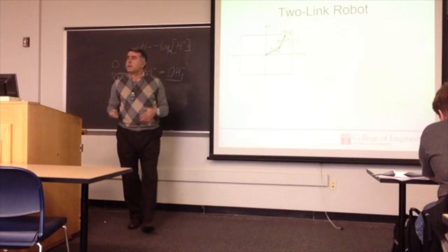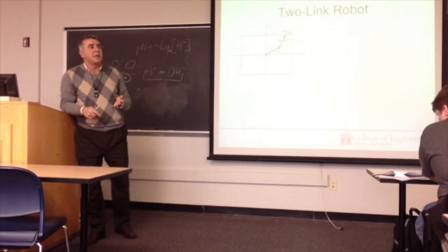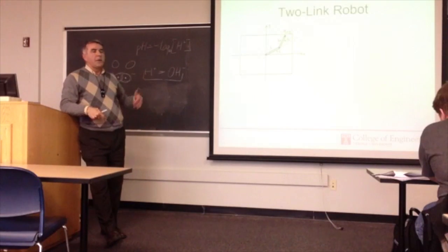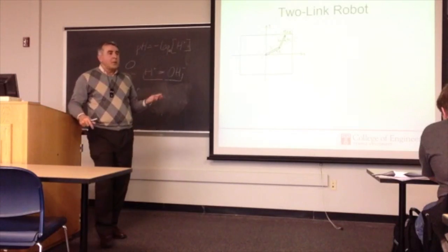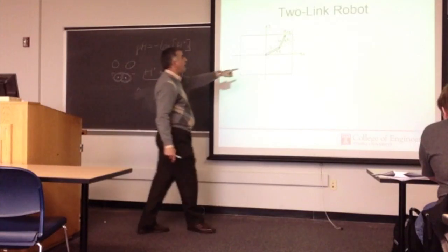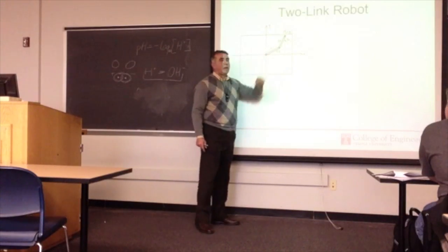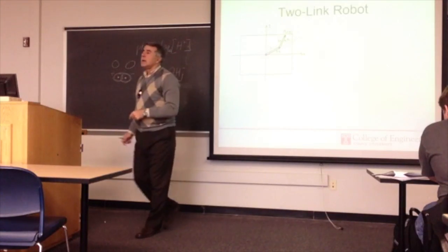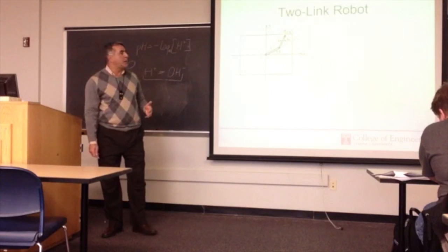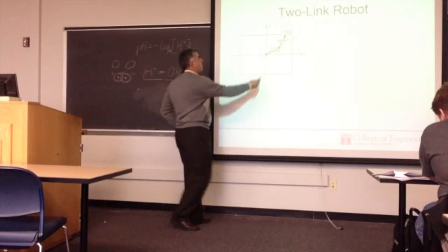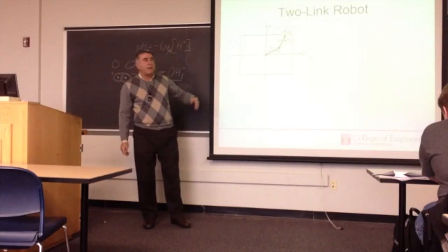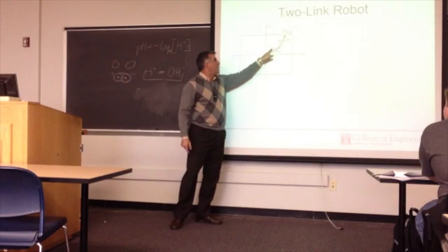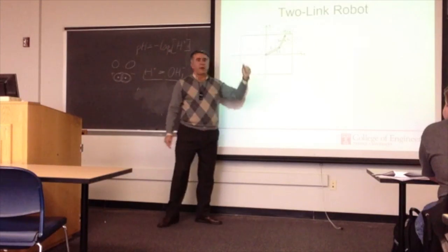Again, same as before, we are assuming that the robot arms are rigid, therefore they are not going to change in size. What we are changing really is the angular displacement, theta 1 and theta 2. You may say, well, why don't we measure theta 2 with regards to the x-axis? But the fact of the matter is the motor is at the tip of that bar.